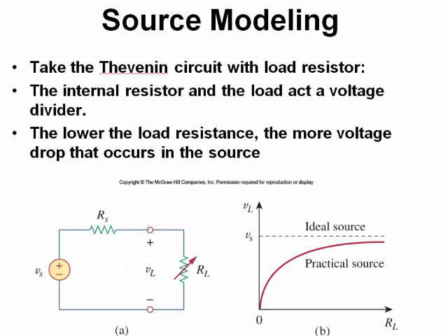So here's a specific example from when we were doing power transfer. I have my source modeled as a voltage with some internal resistance. So this is my power supply now. If I were to short circuit my power supply, I would not be able to put out this voltage source. So let's say I set that at 12 volts, but I short circuited my power supply, I would not get 12 volts out. If I start giving just a little bit of resistance, which is a whole lot of current, I still cannot supply the 12 volts that I maybe want for my circuit.